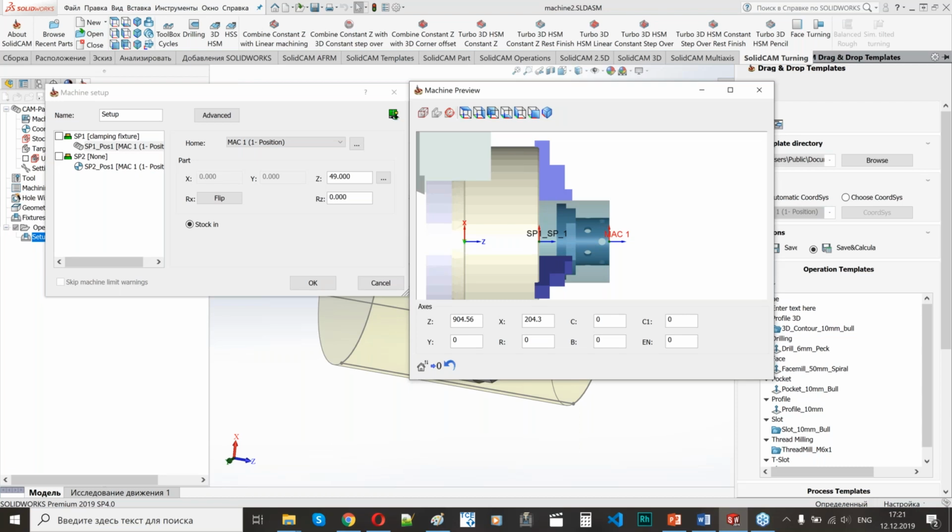I would like to add one more note to this item. You can use data from the setup window not only for simulation and preview. Most modern CNCs have visual functions, even 3D and G-code check before cutting. But to use this possibility, you should describe stock dimensions and stock position in the chuck inside the NC code at the very beginning of the program.